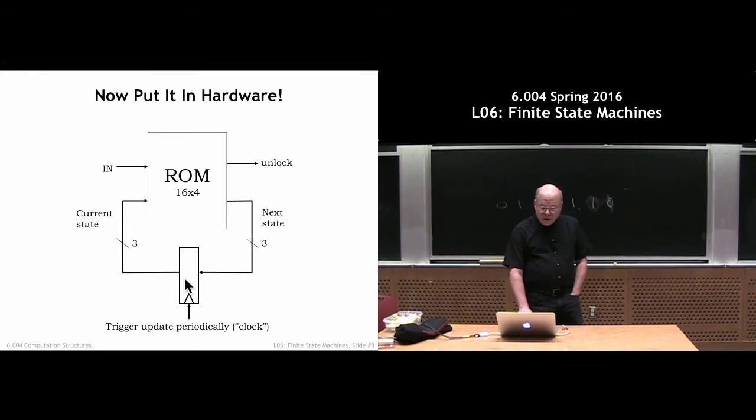It's okay for a register to be both the beginning of information flow within a clock cycle and also the destination of that flow. So at the rising clock edge, a new value comes out here. We compute a next value, and at the next rising clock edge, that value then gets latched in the register and becomes the next current state. Right? So it's a sequence of states, and it's perfectly okay to compute the next state from the current state. In fact, we have to. That's what an FSM does.